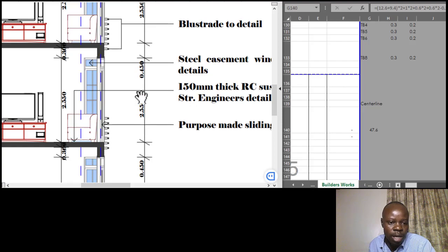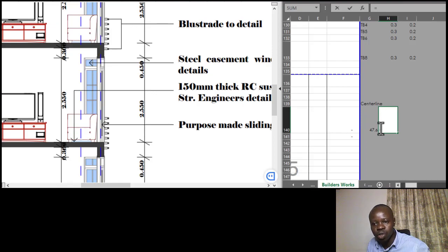So in this case, it's given straight away, and it's 2.55. Okay, so the height is 2.55, so I'll take it equal to the center line that you've already calculated times 2.55. When you do this it gives you the gross area of the wall, but remember that you always want to have what we call the net area for your walling. So net area would mean the next step after you've calculated the gross area, then you need to subtract the openings.